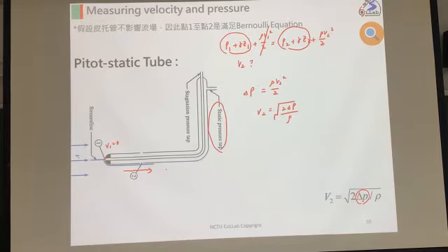The outer pipe is a static pressure tube, trying to measure the piezometric pressure for point 2. And the inner pipe is a stagnation tube, trying to measure the piezometric P1 pressure. So a Pitot tube can tell you the pressures at locations 2 and 1 very quickly.